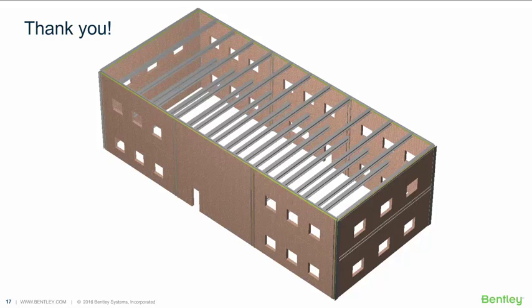Okay. Another one here: do you model differently if you have walls and steel frames in the same direction? Not really. The load distribution itself is taken care of automatically. In a seismic application, there would be the matter of what your seismic parameters are, what your response modification factor is, that kind of thing, which would weigh in. But there's really nothing special you need to do from the modeling standpoint. It should be set up pretty well to handle that geometry.